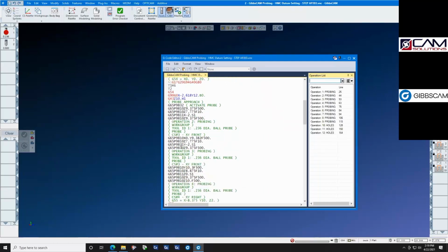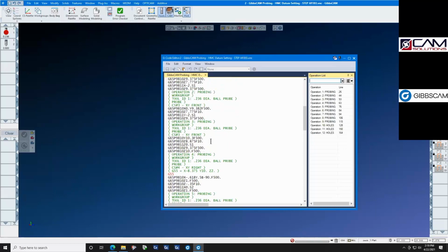The probing is done automatically, and this probing code, of course, you can generate by hand, and that's probably what you've done so far, but it's tedious and it requires meticulous checking before you cut it loose in the machine. Here, we can program the probe offline in a virtual environment with no danger to your machine or your process or your probes.